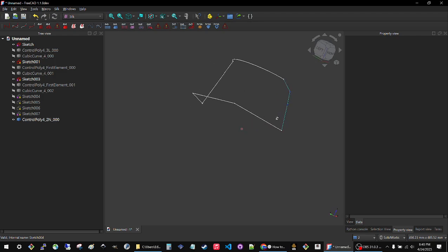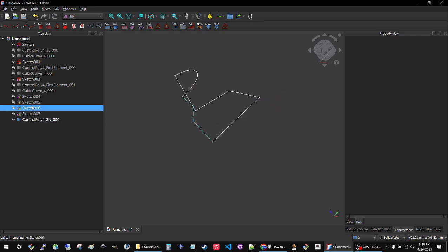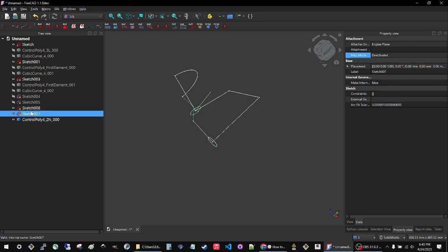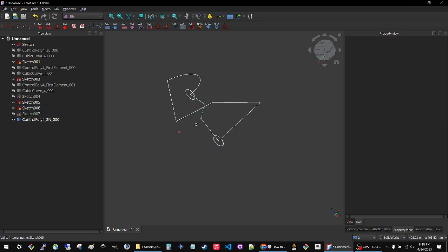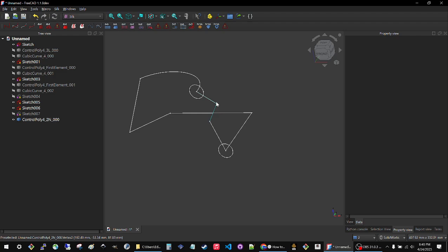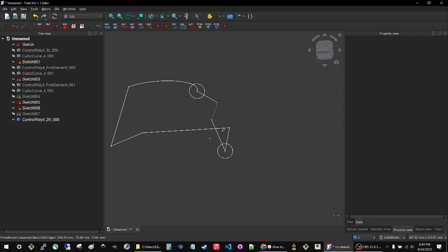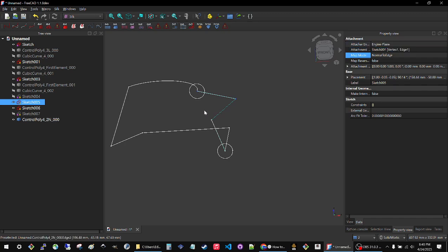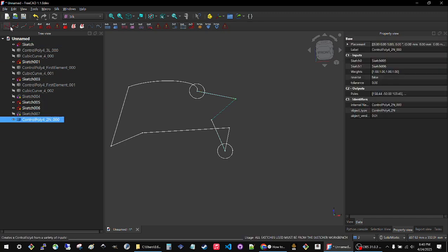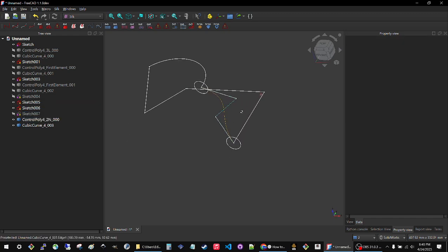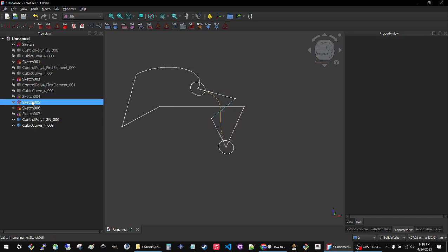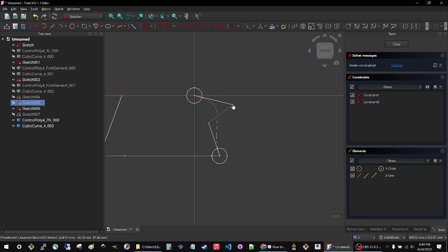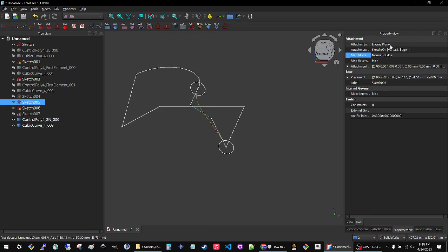Instead of drawing 3 lines in a plane, I created these 2 things that I call nodes, and I put them anywhere I want in 3D space, and it draws a connector. So this is a 3-dimensional connector. It's not in any particular plane. And I can go back in here, and I can edit it, and the polygon updates. And of course, if I add a curve to it, now I have a 3D curve. And this 3D curve I can control completely from these 2 sketches.